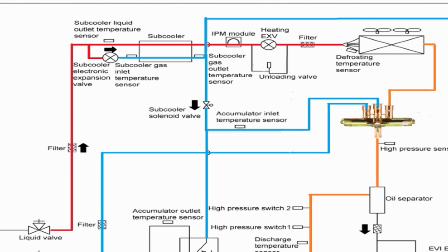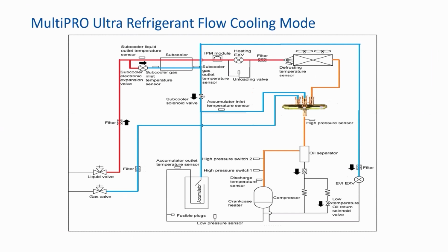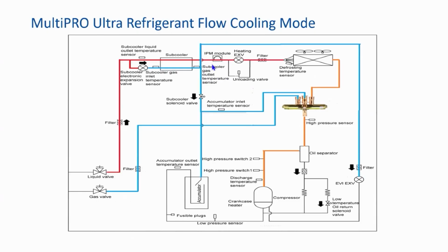And on the service tool, is that just to take the load off of the compressor or the unit itself, or is it to get your liquid temperature down so we get a better flash point at our indoor EEV? Okay. So again, that's going to be dependent upon other load conditions within the machine that our outdoor board is constantly looking at. All the thermistors and stuff like that, just like we talked about in the mini split yesterday. It's constantly digesting all of the data that it's getting to know what the machine needs to do. In other words, the speed of the compressor, the speed of the outdoor fans, the speed of the indoor fans, what step the EEVs are at, whether you're in heating mode or cooling mode. You know, they don't have to be wide open, right?